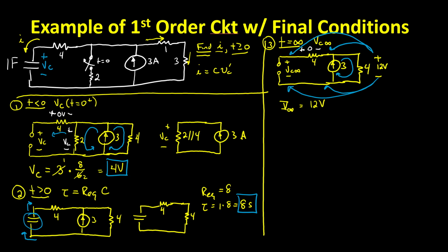Sometimes you might see me put little lines on top and bottom of the voltage symbols like I did here. That just emphasizes that it's a capital V and not a lowercase v. We use capital letters for things that are DC that don't change in time, and lowercase letters for things that do change in time.